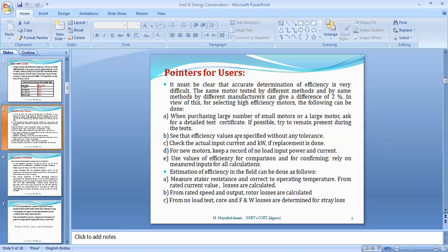In the energy audit, we have come to one important point. That point is that if you are able to measure, don't do the calculation. If you are able to measure the power, the kVAR, kWh and power factor, don't calculate, because in our calculation we are using standard formulas, whereas the measurement gives the actual reading.